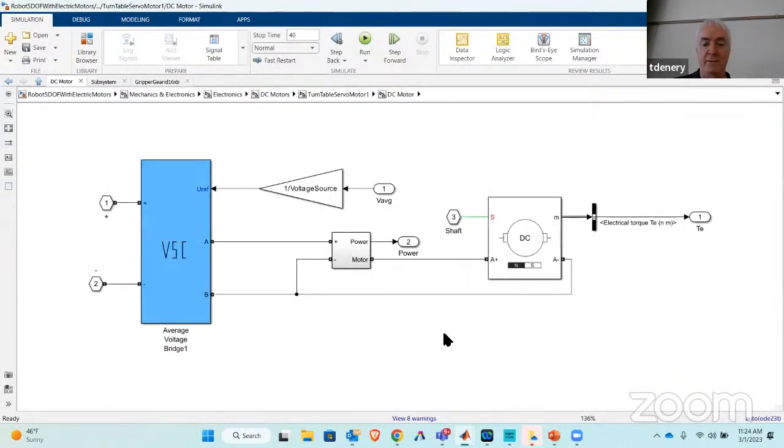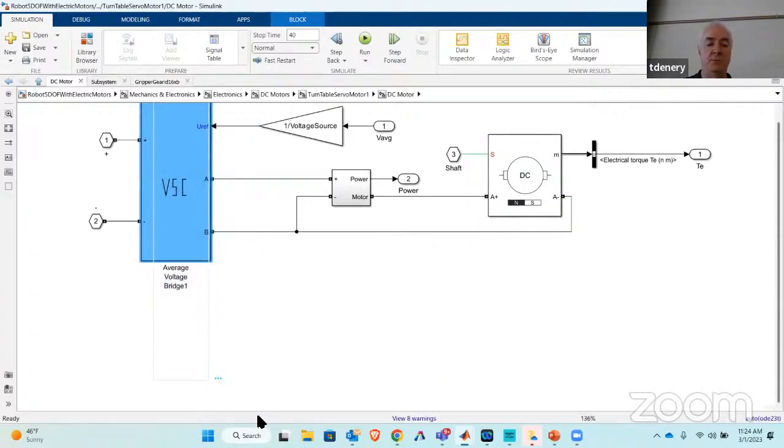I mean, if we go even further, you'll see there is this thing that really is magnets and windings, and the windings are going to carry current, which is controlled by the voltage that you apply to it. Our means of doing that is what we call an H bridge. And we're seeing a representation of that right here, right? Now, are you familiar with the term pulse width modulation?